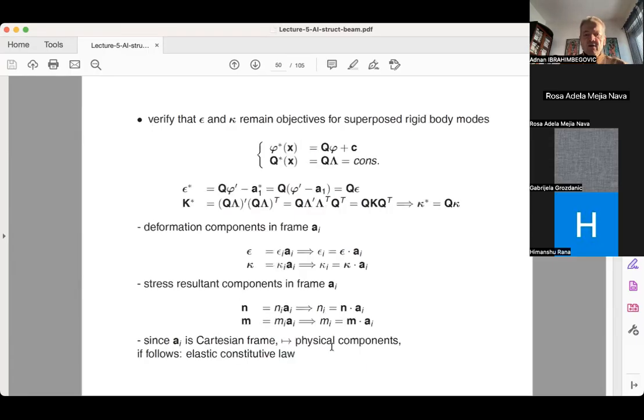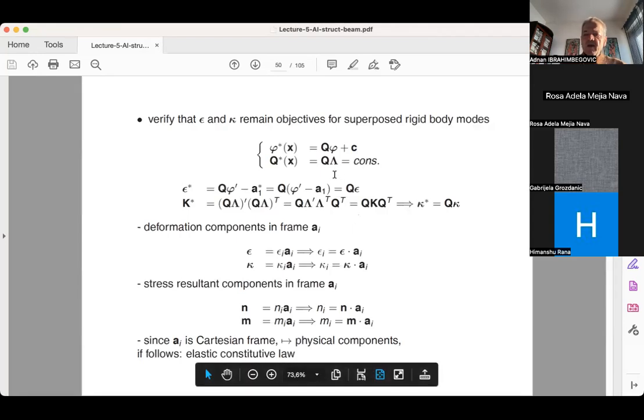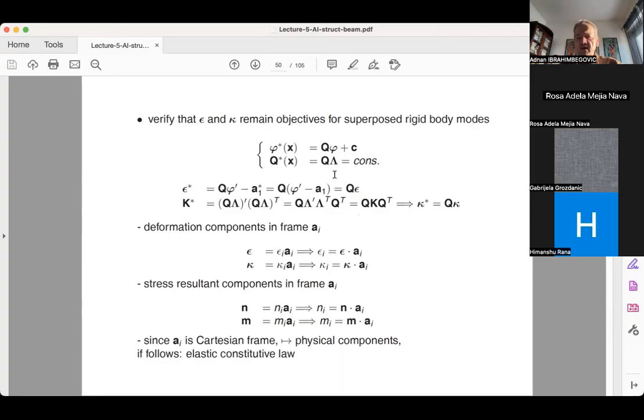Then these are also the strain measures which are supposed to be objective. In other words, when you're in a particular deformed configuration, you already have corresponding deformation. The corresponding deformation is given from the new position vector, which I call phi, and the rotation of the unit triad GI into the triad AI, which is given by lambda. So now phi and lambda are not constant, but they are a measure of the previous deformation.